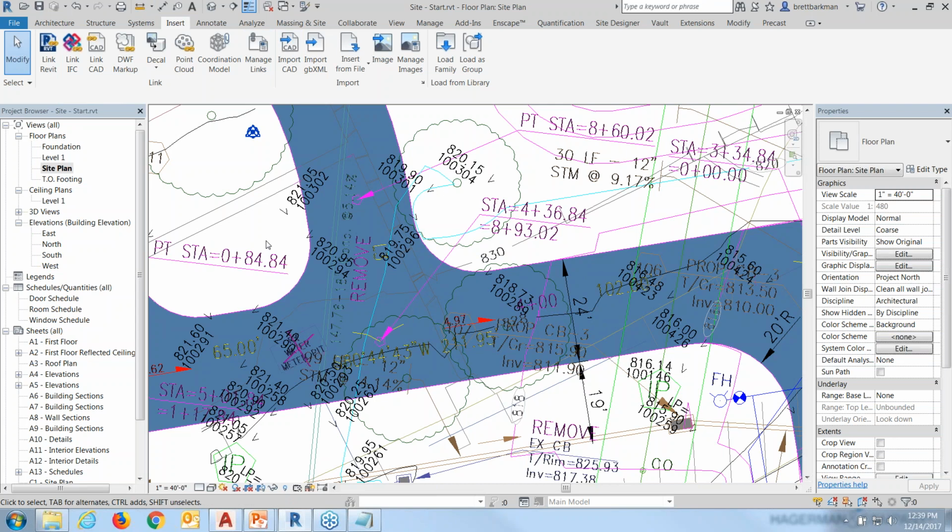So you might want to just make a note of it, that as soon as you bring in a 3D file, measure something or use whatever method you want to use and verify that it is the right size. In my case here, it's not. So we need to scale this drawing.